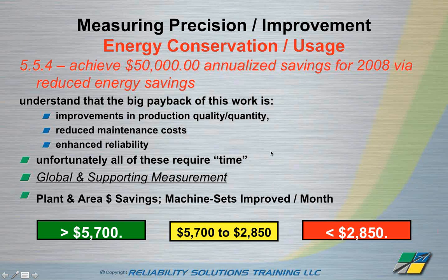Energy consumption, of course, is a place where ultrasound plays in terms of air leaks, but also precision maintenance. When machines are in a precise state, they consume less power. It should be something you track. And a lot of times, if we do a class for, say, 15 craftsmen, and they all go and put a single machine into a precise state within 30 to 60 days of finishing the class, then the energy savings accrued from that will typically pay for the class itself.